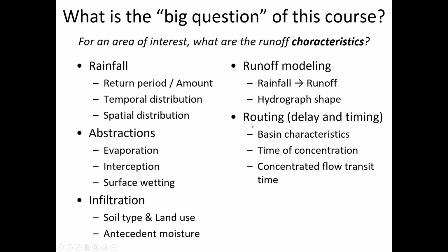A bit later, once we get into these computerized models, we'll look at how the hydrograph shape is affected by different techniques that we use to estimate time of concentration. So you remember that we talked about how there's kinematic wave, there's the Kirby method, the FAA approach. There's all these different formulas that have their own little niche applicability for predicting how long it's going to take between when the rain begins to fall and when it arrives at a certain location.